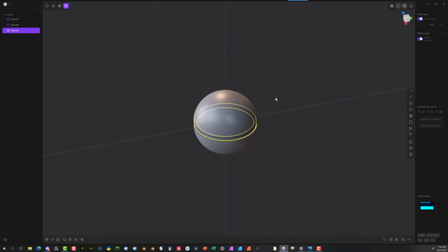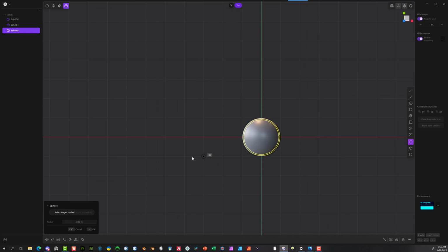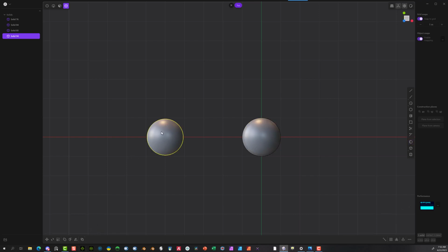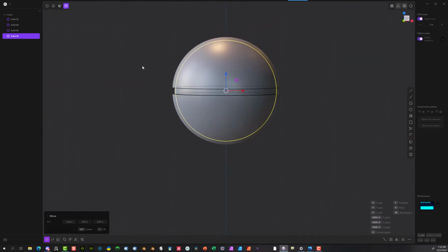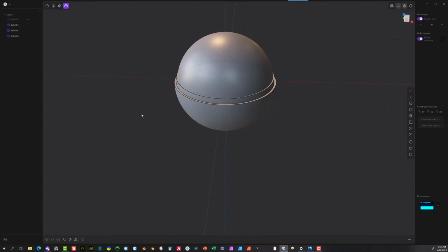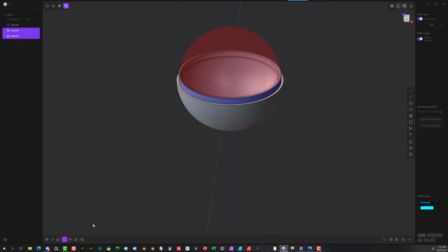One thing that we will need to do is kind of cut this again, because this is not going to be right. So if we go to the top view, we can create the sphere again. Again, let it drop, put 0.94. Say OK. Hit the G key, bring it back through. And one thing we can do now is get closer. Go ahead and hide. Say OK first. Go ahead and hide this top section. Hide. So now we can select this again, and then this, and now hit the Q key. Say OK. That way it's completely solid around. It's actually even throughout. That's what we're trying to do here.